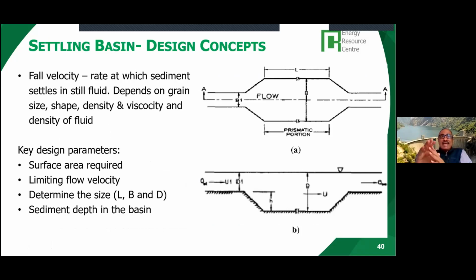And the basic design concepts, I will not go into much detail, but I just want to give you an idea of the design. When you design a settling basin, you basically find the fall velocity of the sediment. So what you have here is the canal. Then you have a settling basin, which is a little bit wider.